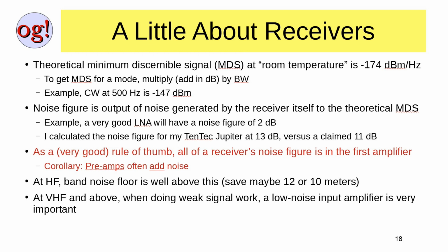So if you've got a tiny signal and tiny noise, you add the two together and multiply that, now it's not so weak. So the next amplifier is seeing a stronger signal and then adds a tiny amount of noise. Not going to make any difference. You go further down the chain and you're dealing with volts instead of microvolts. And the microvolt that amplifier adds in noise just isn't going to make any difference.